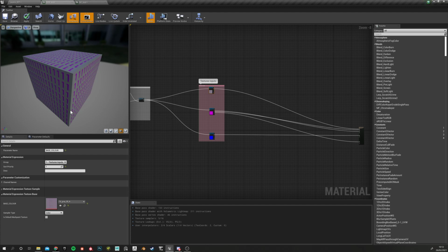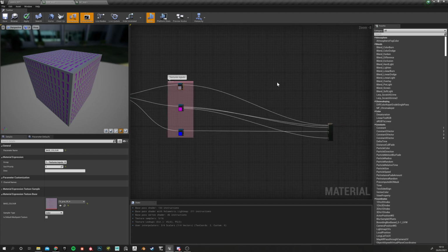You can actually, instead of creating a green texture, take the red and then tweak it until you get the color you want. And for that we need the logic here that will allow us to tweak that. So I'm going to create several groups. One is going to be base color tweaks, another one is going to be called roughness tweaks, another going to be called metallic tweaks, and so on. So we're going to have things organized. I like to work organized.